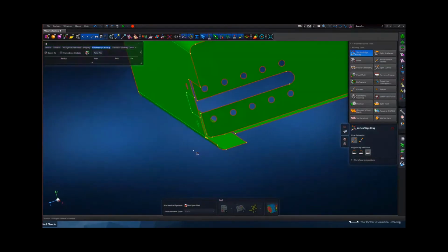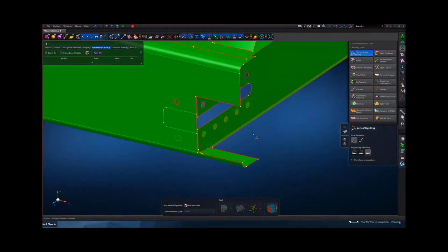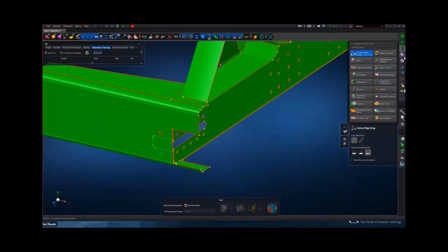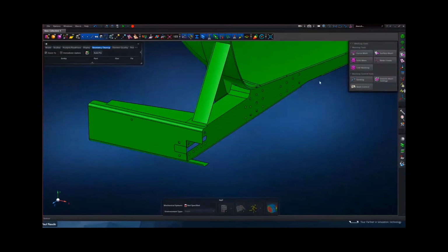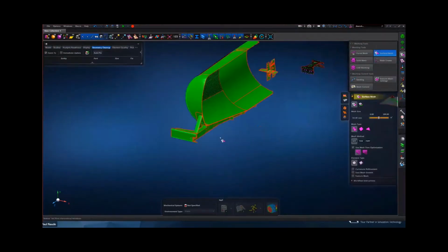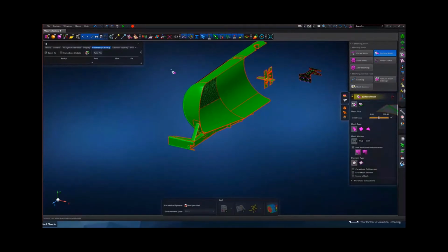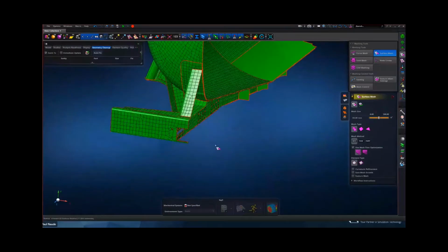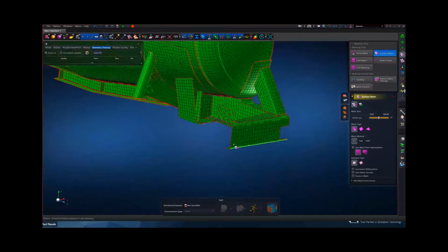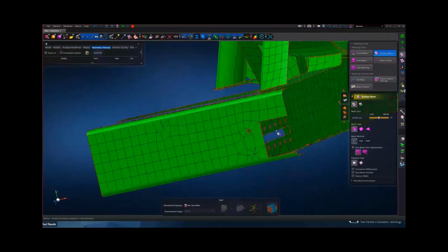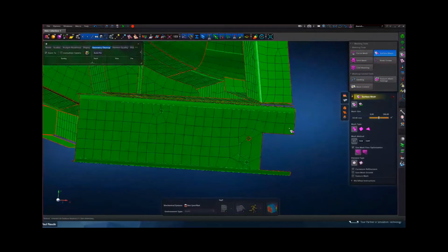And this is all in service of getting a better mesh. What is a very handy tool to use is actually to mesh your part, but you can actually mesh it with a very coarse mesh. A coarse mesh updates much quicker, and they also tend to show you defects much better.